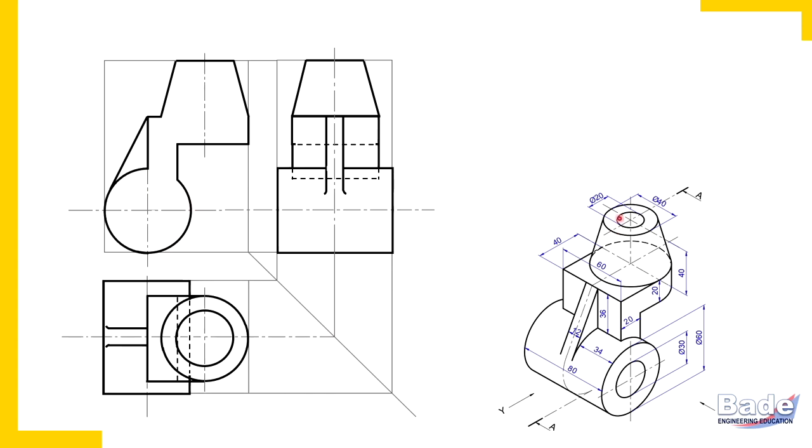Now let's draw those two holes. Okay, this hole in the cylinder first. 15 mm is its radius. A circular opening appears in the front view, so corresponding dotted lines in the top view. This hole is in the cylinder. So watch here, these two dotted lines, this dotted line and here it is a dotted line. So this complete rectangle is that hole in the top view. Okay, let's draw this rectangle in the side view. Draw end projectors. Watch here. And these two dotted lines indicate this hole in the side view. In the front view, this is that hole.